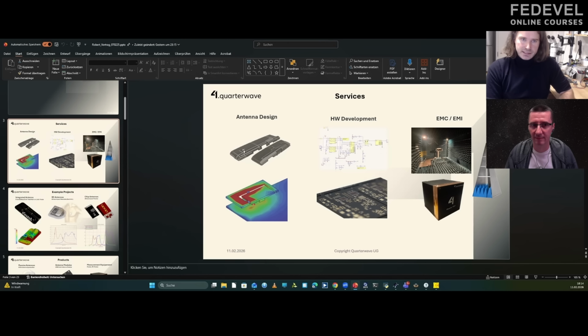It's similar to signal integrity. That's also a part of what we cover. So we're also doing signal integrity simulations, power integrity simulations, and to close the loop, we also do pre-compliance measurements. And I recommend everybody to do pre-compliance EMC, EMI measurements. Otherwise, you get big trouble in the test laboratory. I have had many bad experiences, so it's good to do it from the beginning, and also the antenna design, to do it in the beginning.